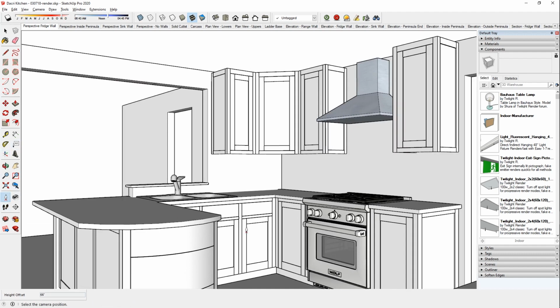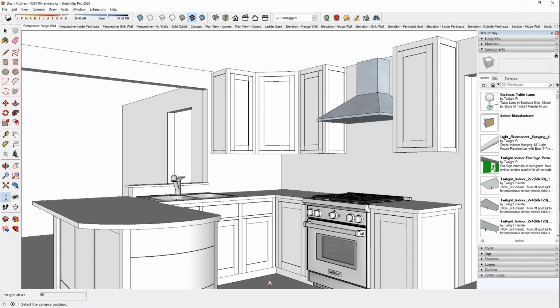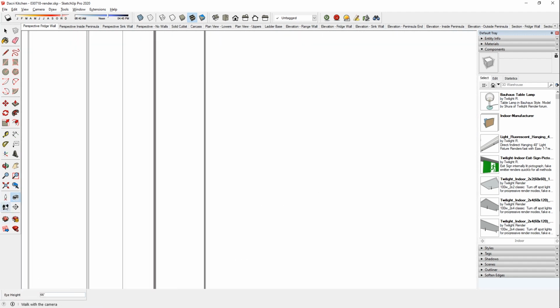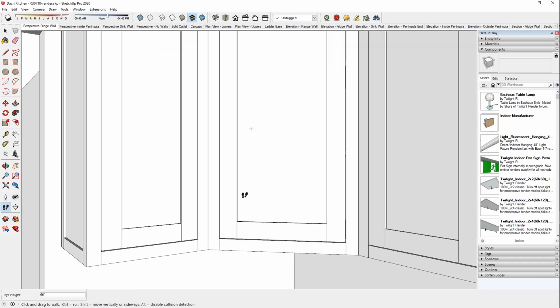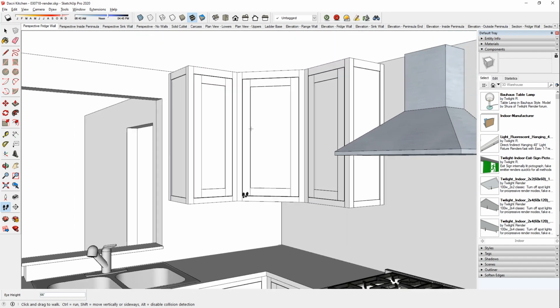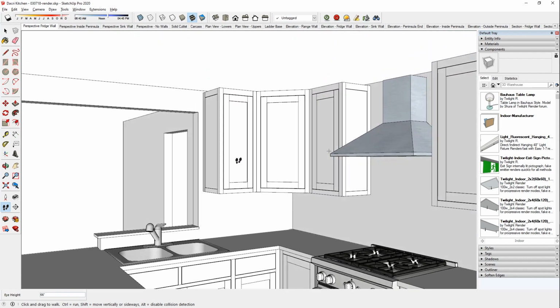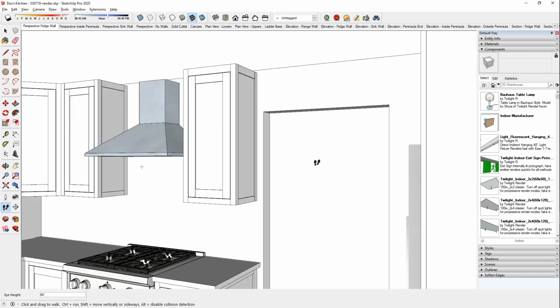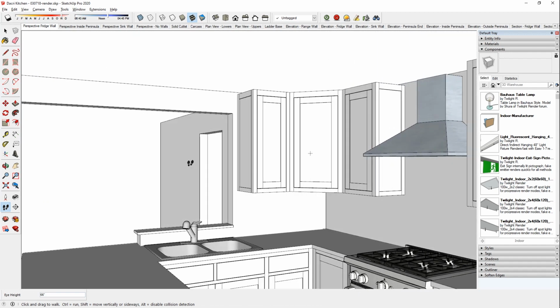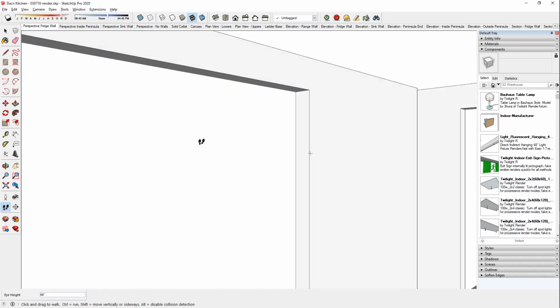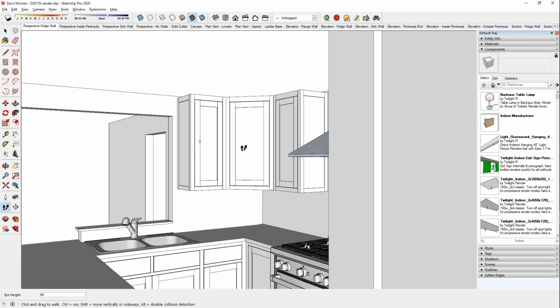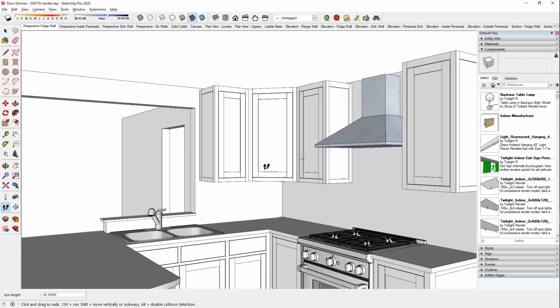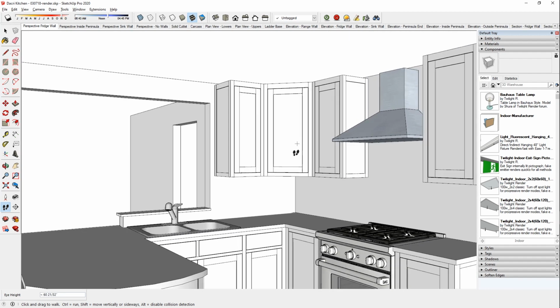And with that guy, you just simply click once and let go. If you click and drag, it will try to place the camera at that height. So just click once and let go, and that straightens your verticals out, which is very important in rendering interior images. In any architectural images really, you'll want your verticals to be straight up and down. And this positions your camera so that it's perfectly horizontal.